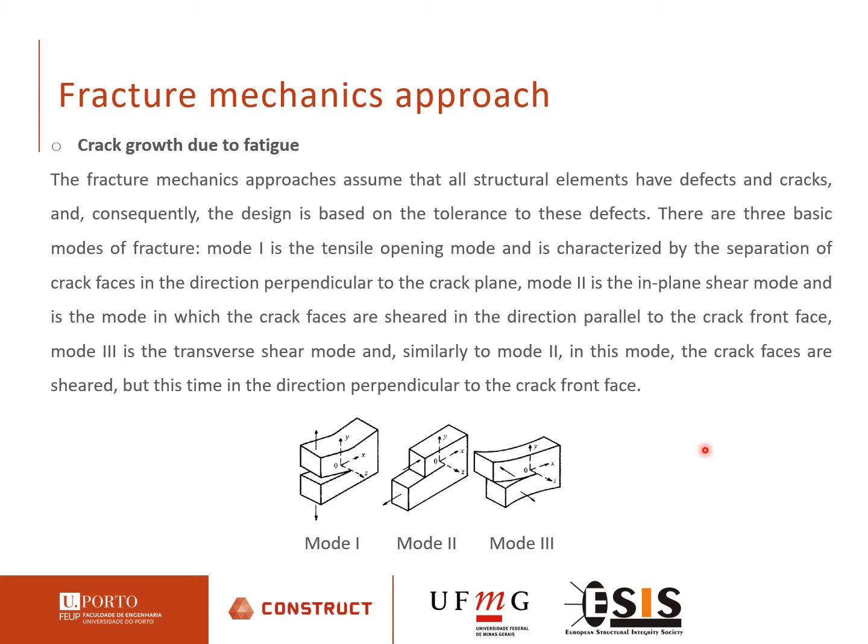The fracture mechanics approaches assume that all structural elements have defects and cracks, and consequently, the design is based on the tolerance to these defects. There are three basic modes of fracture. Mode 1 is the tensile opening mode and is characterized by the separation of crack faces in the direction perpendicular to the crack plane. Mode 2 is the in-plane shear mode and is the mode in which the crack faces are sheared in the direction parallel to the crack front face.